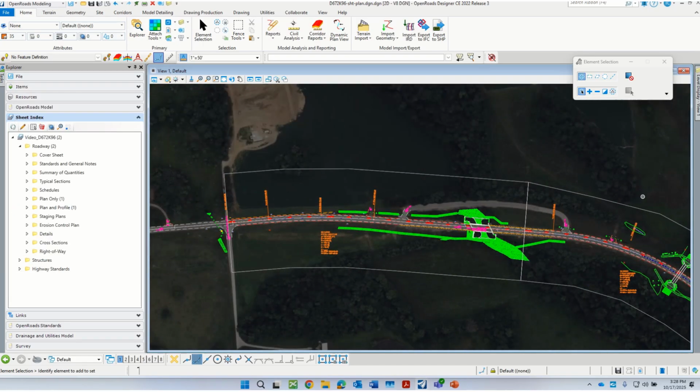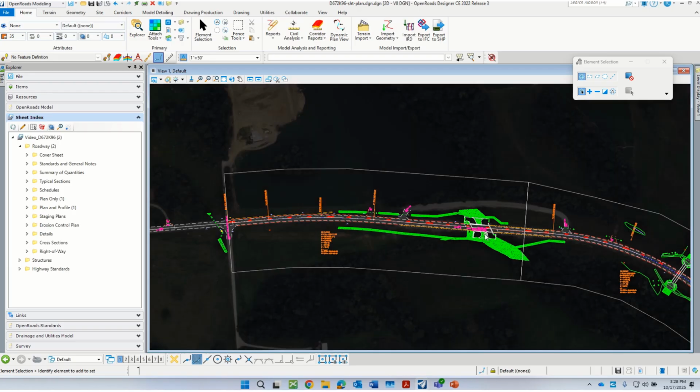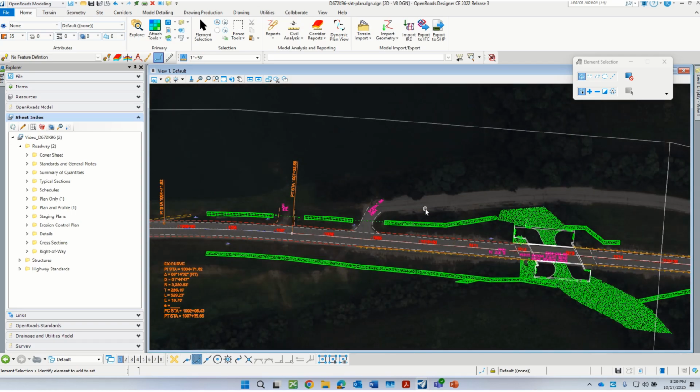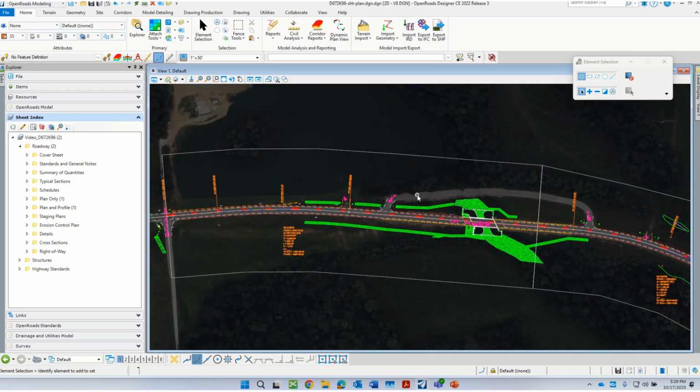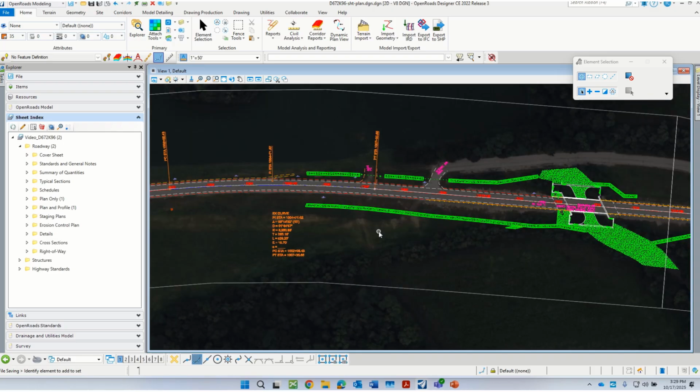Let's see, do you see a difference? Let me do something more drastic so you can tell. Let's do how about 70? What's that look like? There, so you can kind of barely see it. So we'll try maybe 60. That'll just make it pretty faint. You can always change that at any time. So yeah, that's how you can set the transparency just for the plan sheets.